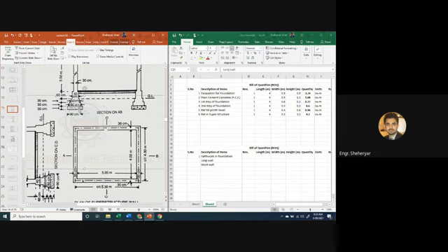Repeat again, sir. Sorry? What did you say? We have to calculate the length of the long wall and length of the short wall at this level, which is having a width of 90 centimeter, because we want to do excavation. So excavation must have at least a width of 90 centimeters.